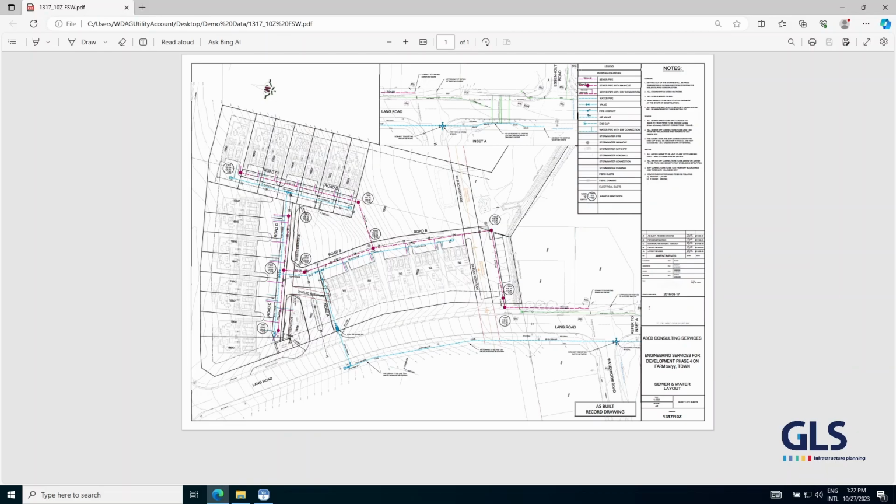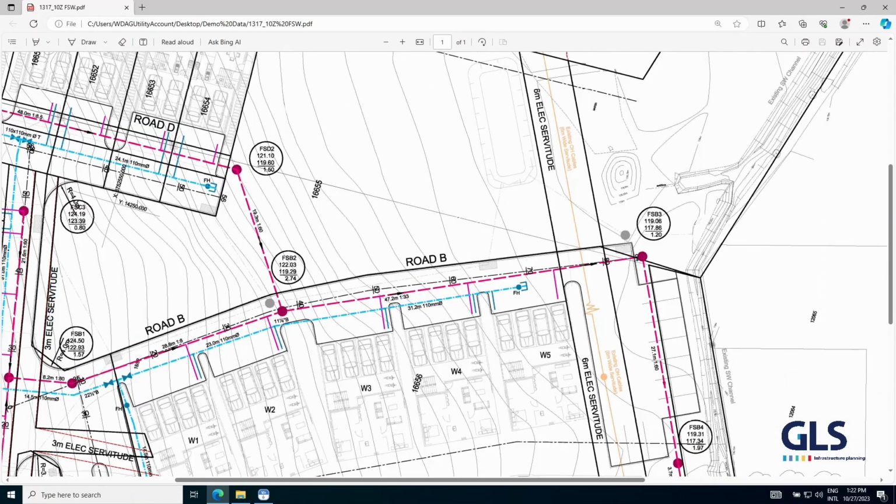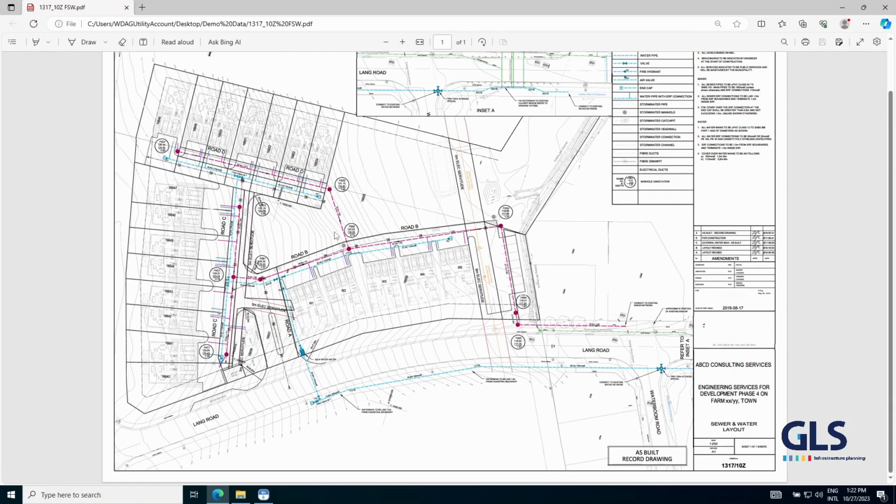And also the x value is increasing in a southern direction, which means that the coordinate system we are seeing is the southern hemisphere coordinate system, with y increasing to the west, and x increasing to the south. That information also is all important when you try and fix this to the correct location.